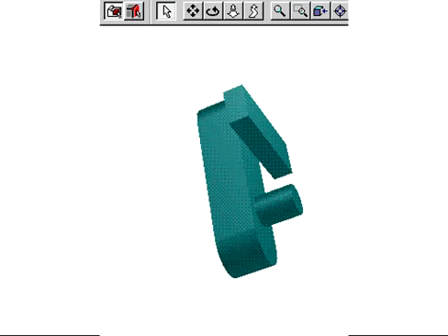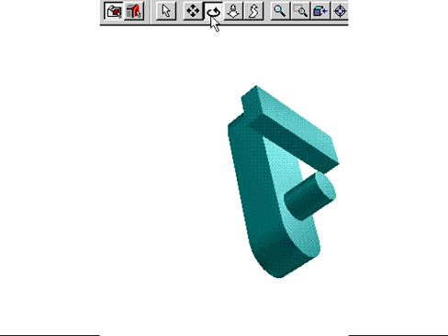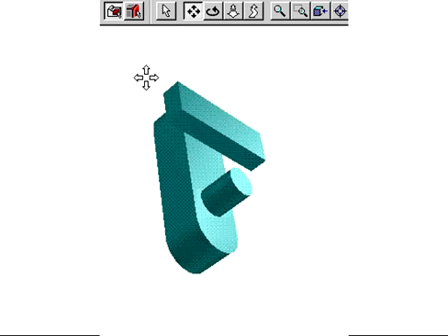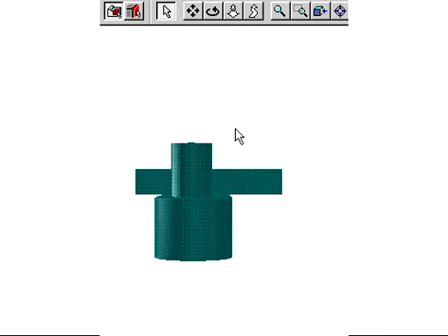Use the camera tools to view your model from different perspectives. To rotate your viewpoint around the model, click the Orbit Camera tool and then click and drag within the scene. Use the Pan Camera tool to move your viewpoint around on a 2D plane in front of the model. To view a particular surface on the model straight on, select the Look At tool and then click the surface. Try the other camera tools to see how they change your point of view.